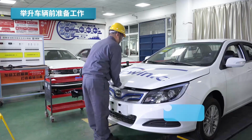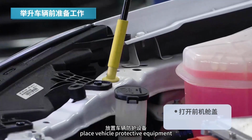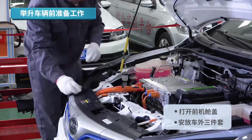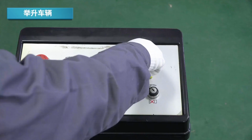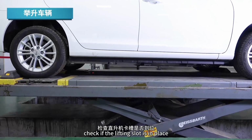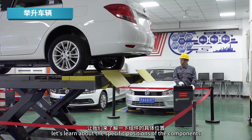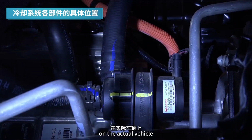Open the front hood. Place vehicle protective equipment and seat cushions, floor mats, and rear seat covers. Begin to lift the vehicle after reaching the lifting position. Check if the lifting slot is in place. The vehicle's bottom plate, we have already removed it. Next, let's learn about the specific positions of the components of the electric vehicle cooling system on the actual vehicle.